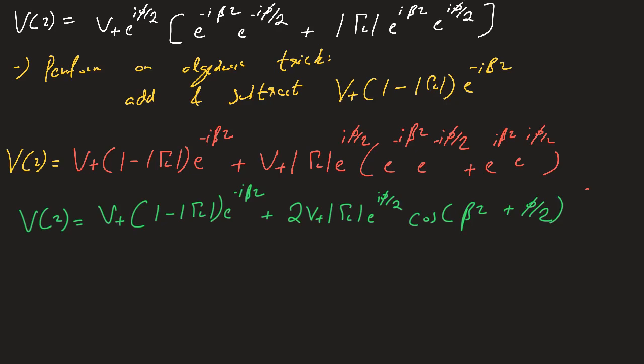And just so that we're on the same page, I just want to reiterate that V plus here is the source voltage amplitude, right? Whatever source that we've connected on the left hand side is the source for V plus e to the minus gamma z, right? Which is why then you have these reflections, and what we're just computing is the net resultant after these reflections.